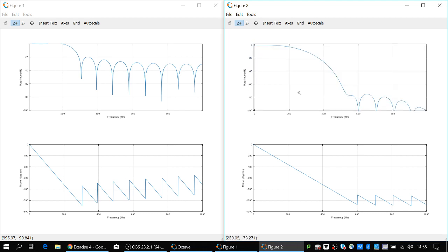Okay. So what happened to the stop band attenuation? Now we have about 70 decibels of stop band attenuation. Cutoff frequency is still the same, 250 hertz here. The transition bandwidth got haywire. So now it's basically the transition bandwidth was about 50 hertz before. Now it has a transition bandwidth of about 300 hertz. But we know how to deal with that one.